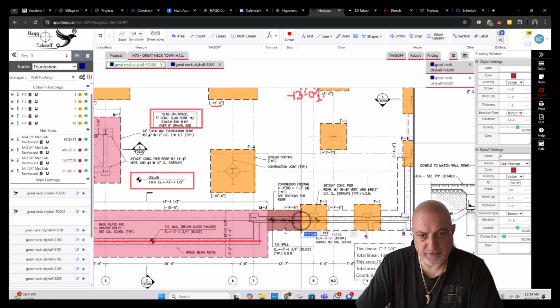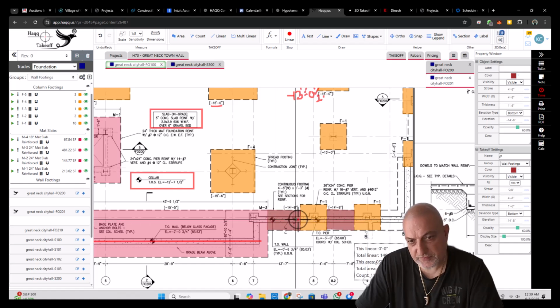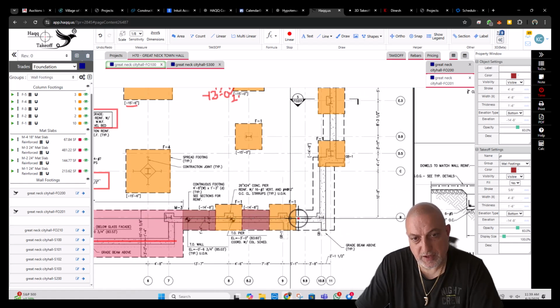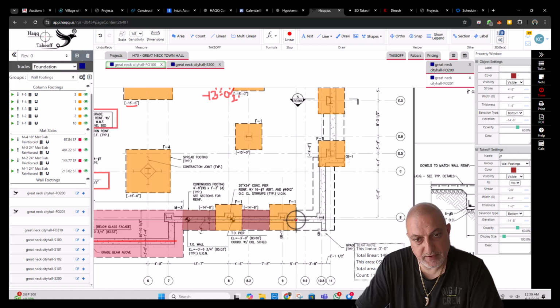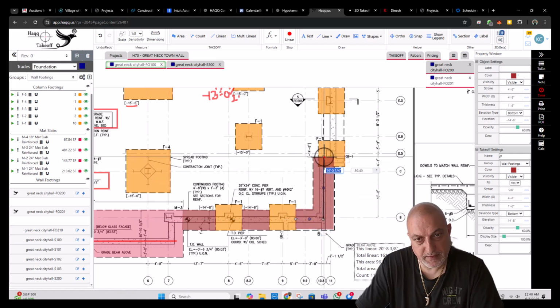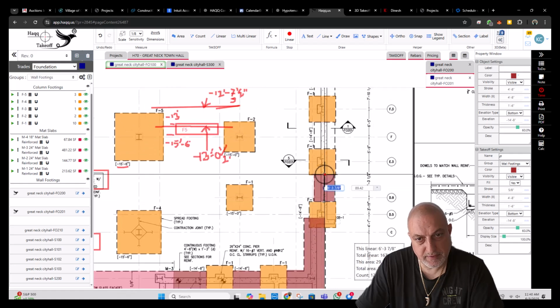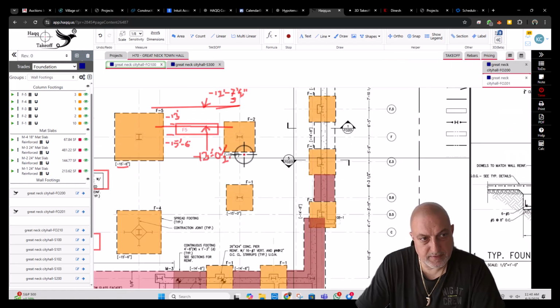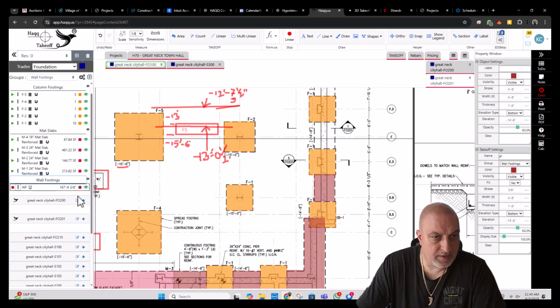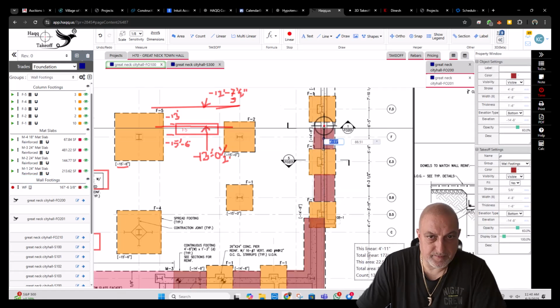And the reinforcing, we will have a problem when doing this piece by piece, because reinforcing for the footing will continue through the column footings. It has to. I'm just lapping here because it's coming up. Let's continue again.